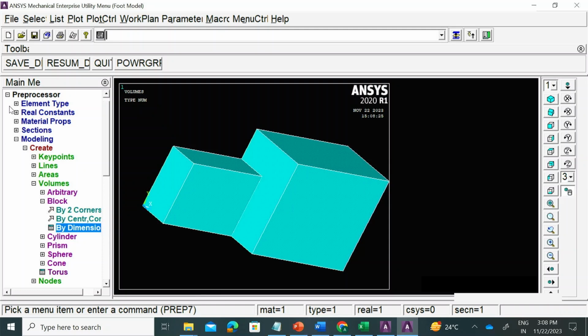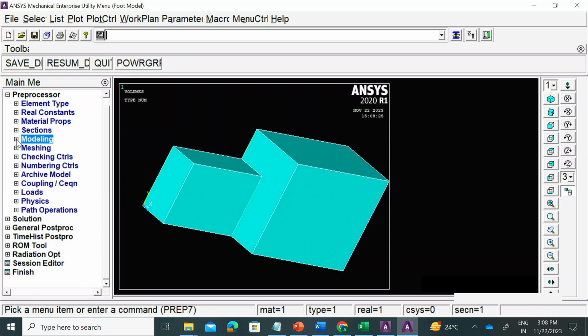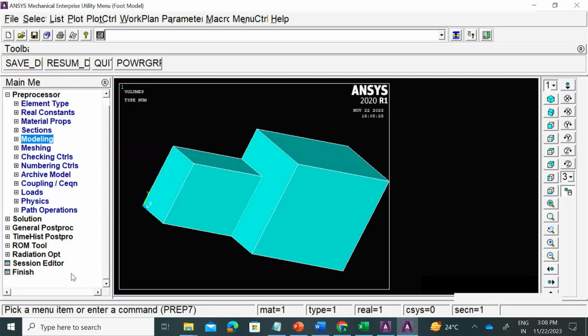Okay, so next thing is we want to create an interaction. So this contact pair based interaction, before we can create that, we have to mesh the 2 bodies first. Please take this as a note, in order to apply a contact pair, we need to mesh both the bodies first. So meshing means there needs to be a declared mechanical property as well as declared element type.